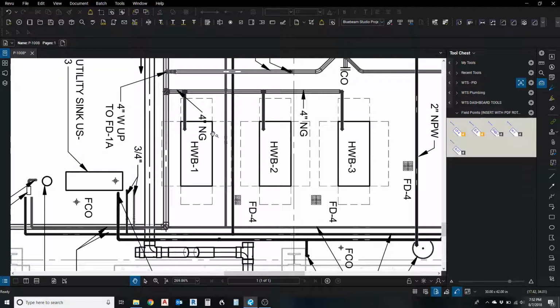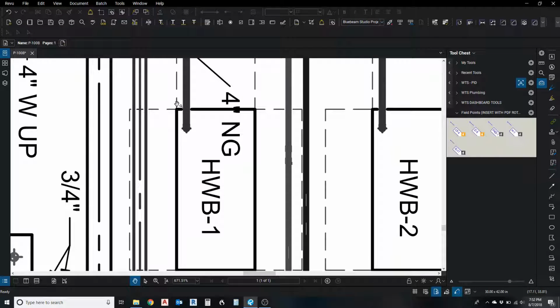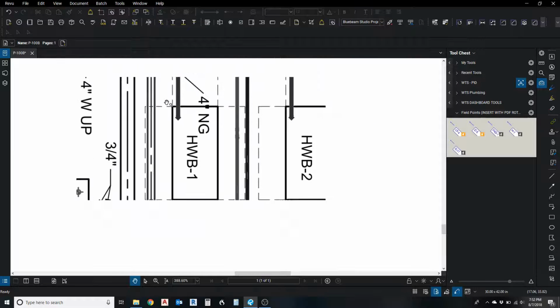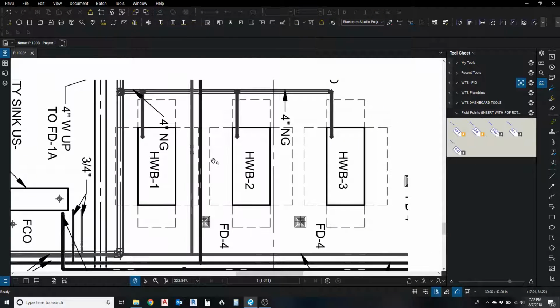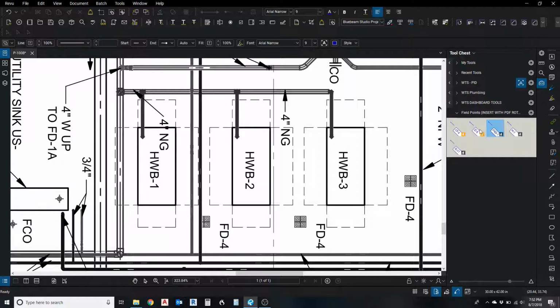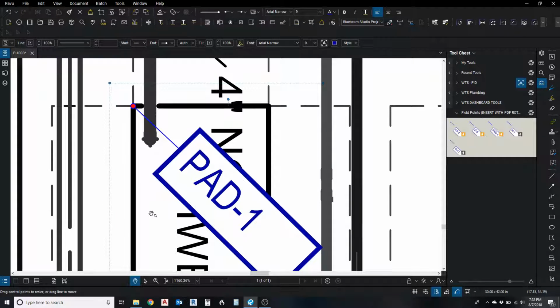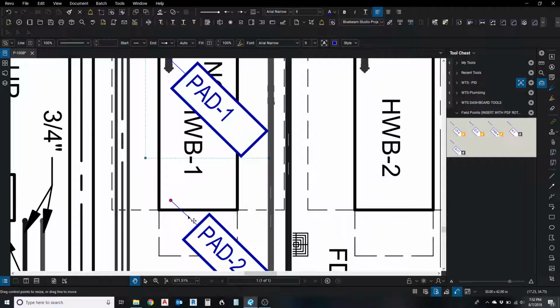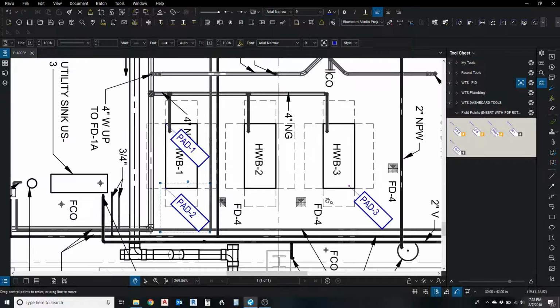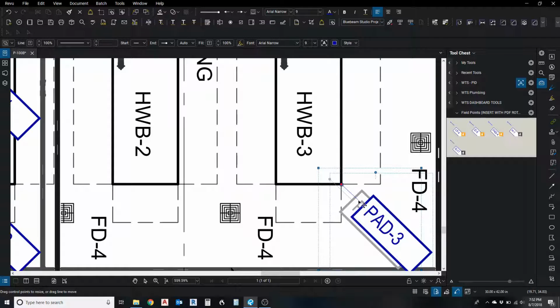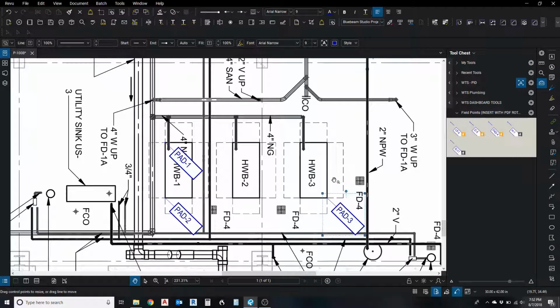The other thing I can do is lay out the housekeeping pad, and I'm going to tell you there are some ways to do this. One is you can come in here, you can sketch up 4 inches and over 4 inches, and you can put some points on. The other thing you can do, which I think is easier, is that your field guys are not stupid. They are craftsmen. So if you take 3 points like this, and you go ahead and snap right to these corners, you can say, hey, I'm going to lay out points that are 4 by 4 off of the corners I want for my housekeeping pad. So you guys lay it out 4 inches off of that.